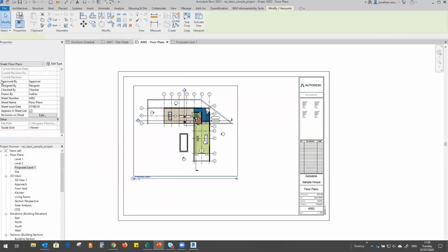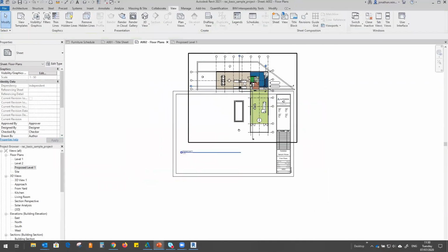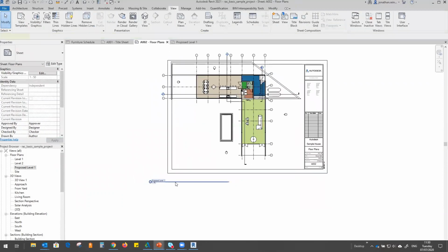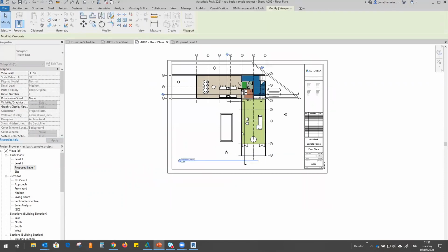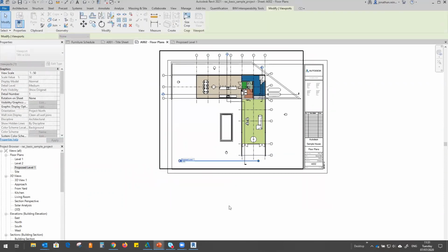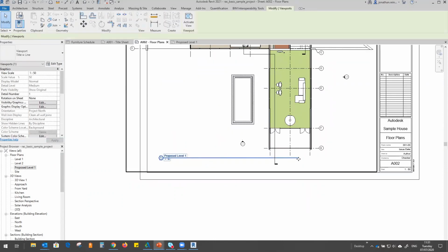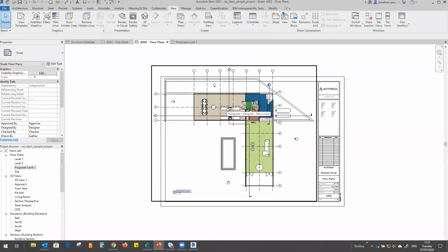So in order to change the scale on this, go up to my left-hand side, go to say 1:50, hit apply on that. Simply drag your drawing down. And this is the reason that I duplicated it, because the other floor plan is only at 1:100, which is fine, but maybe you also want a more detailed floor plan shown at 1:50. So you can simply drag the elements, your title block elements. So here we have, I just stretch that across, just tidy that up. You can also customize these if you wish.